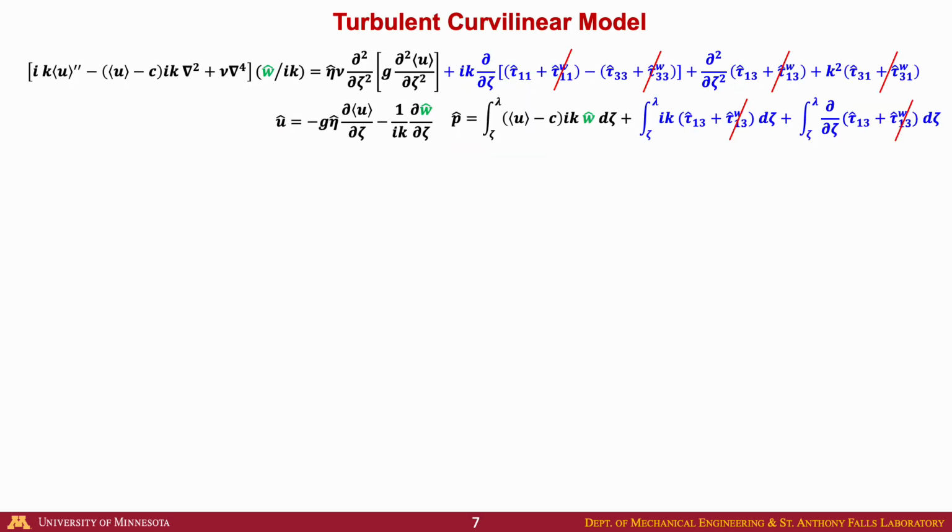Now, in this study, we extend the viscous curvilinear model by retaining turbulent stress terms while still neglecting the wave-induced stress terms. The terms marked in blue are the turbulent stress terms. We call the resulting equations the turbulent curvilinear model.